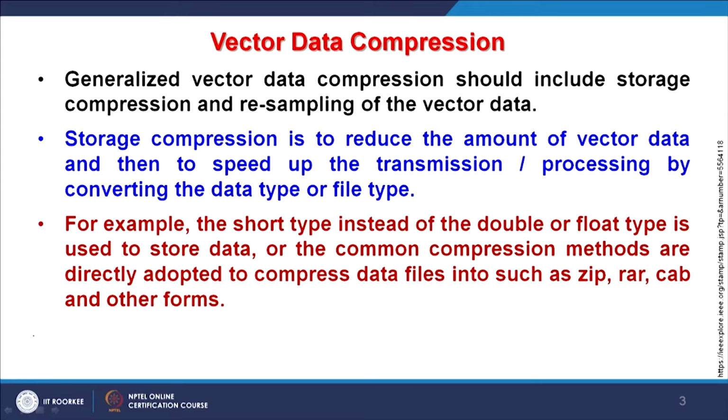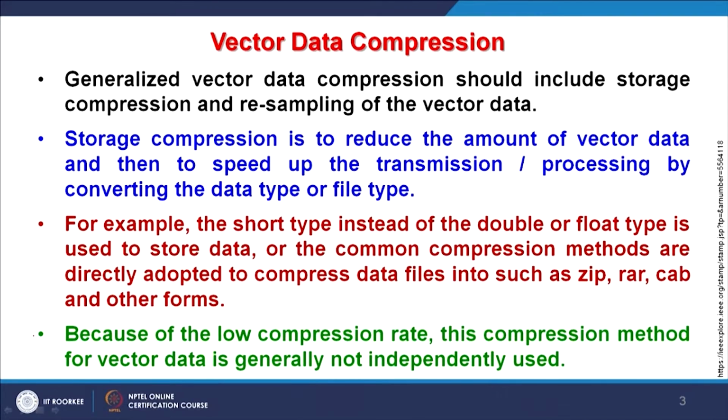So, it is always advisable in real practical GIS projects that first we should decide how much area I am going to cover in a particular study or project. Once that is decided, an area of interest, a polygon boundary, maybe a natural boundary, maybe a political boundary, should be used, and data using that boundary should be extracted and kept separately, so that I will not be using the big data file, but a subset of the original data set.